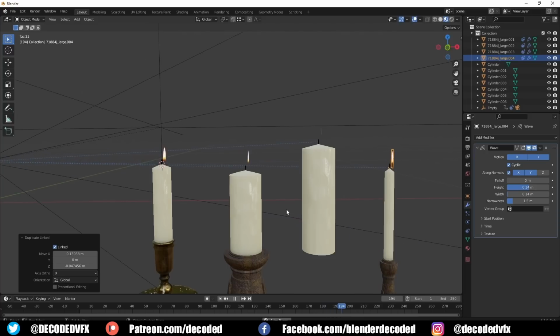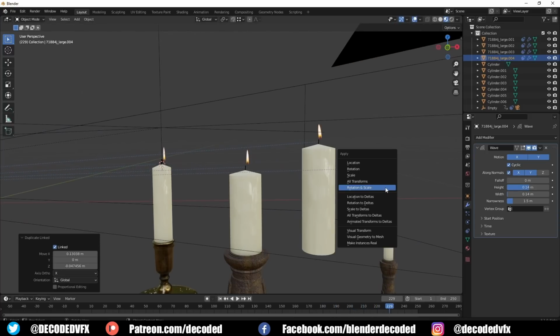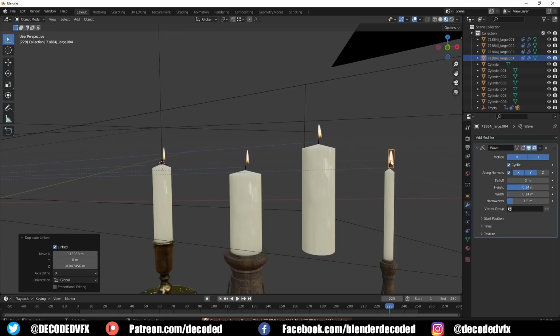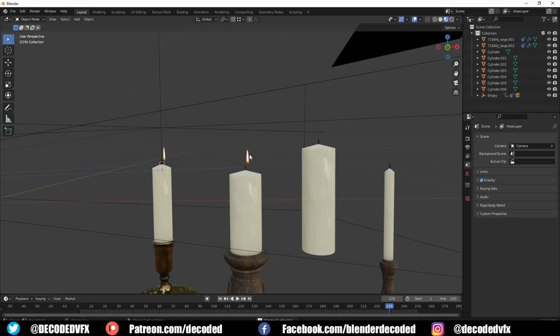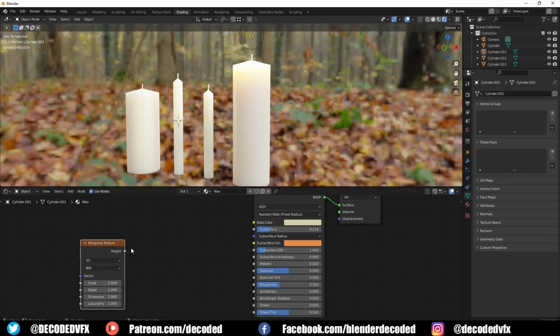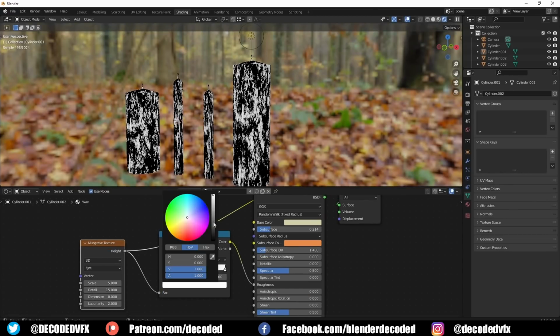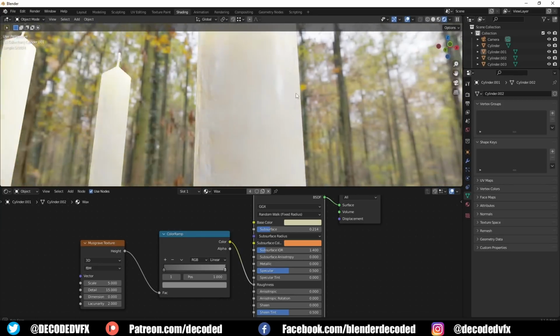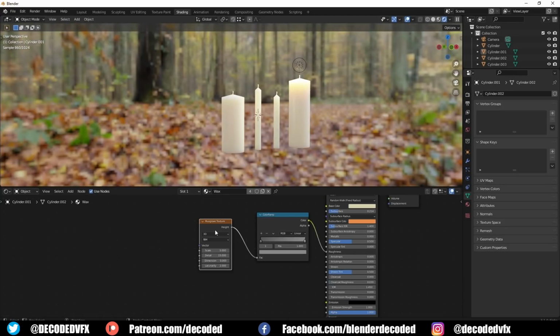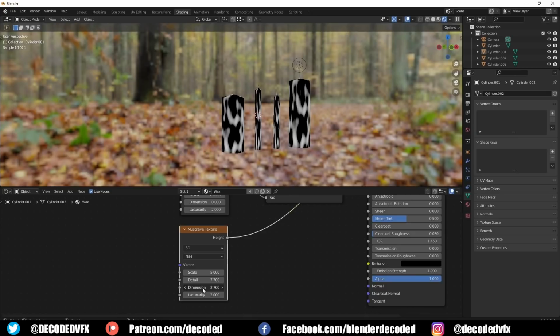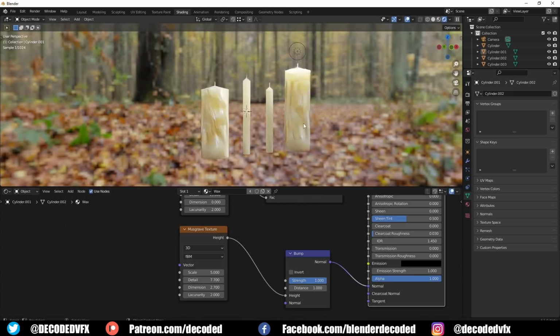Now obviously subsurface scattering for the wax tends to produce a lot of noise in renders, but I find that the Optix rendering does a really good job of quickly rendering out scenes even with SSS in them, and it usually isn't a problem just to bump up the sample count until the final render looks nice. Of course you can also use the Optix denoising as well to take out the last bit of noise in there if upping the samples isn't really an option.